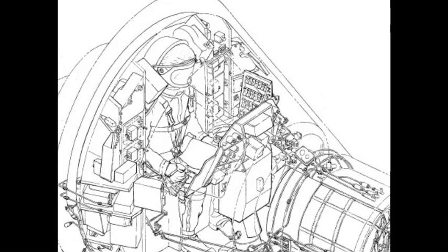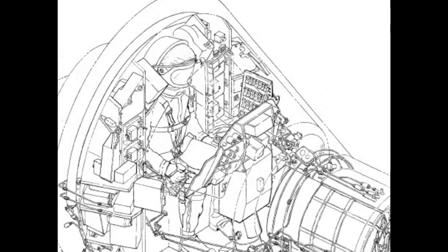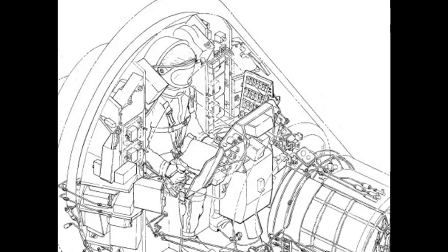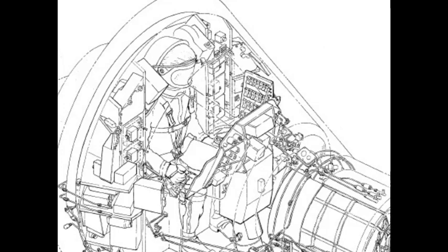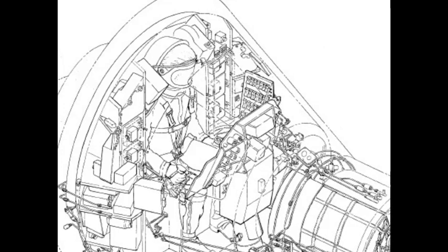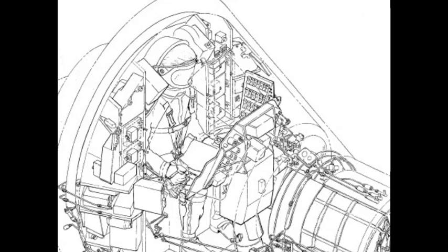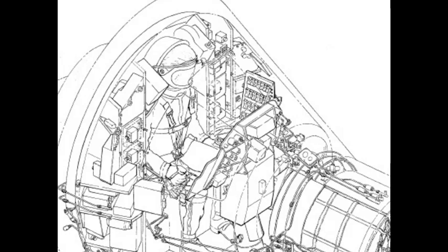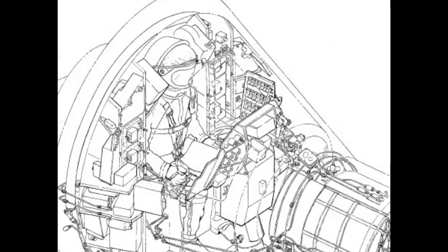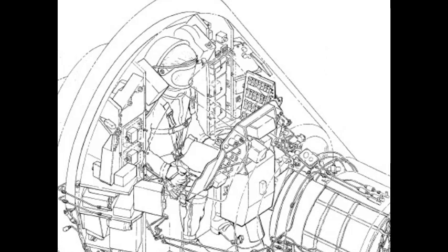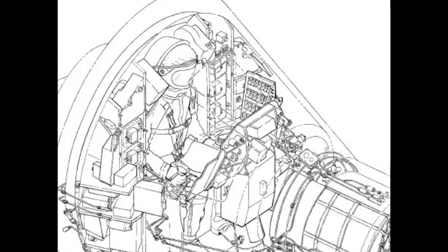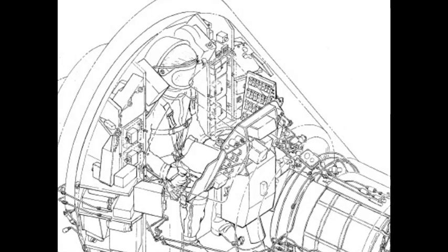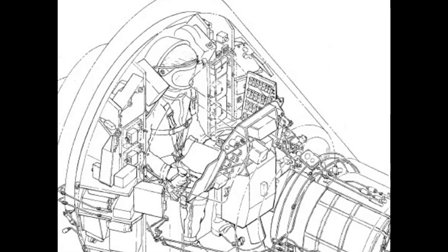Located in the bottom of the conical section, as viewed during capsule normal flight attitude, is a retractable door that encloses the periscope lower lens flange and the capsule ground checkout umbilical receptacle. The door, mechanically linked to the periscope housing, automatically opens and closes with periscope extension and retraction. 2 auxiliary hoist fittings attached to left and right side of the capsule provide ground handling attach points. The hoist fittings are removed prior to capsule launch.